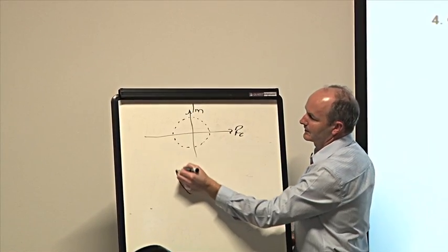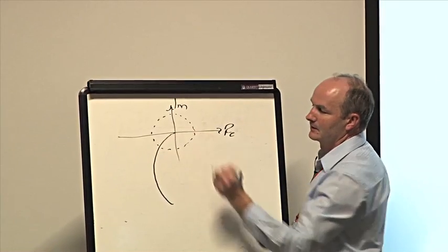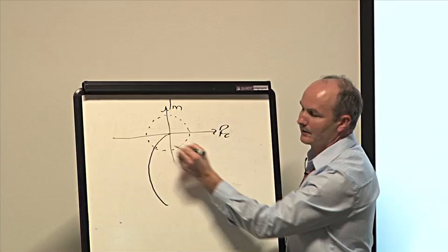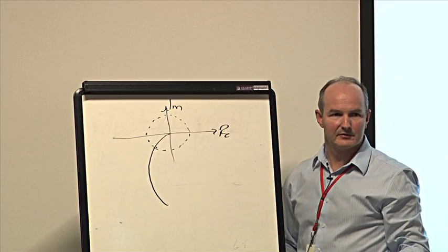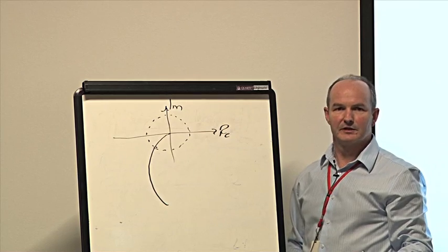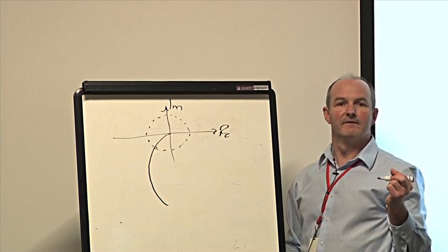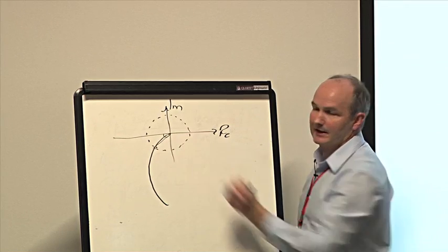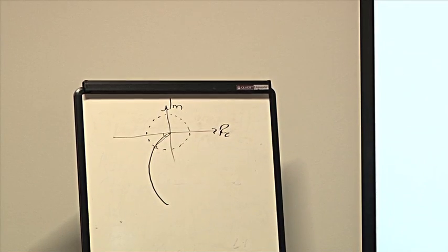If we've got a Nyquist curve coming in something like that, what's significant about that point? The gain of the open loop is 1. It's the gain crossover frequency, the frequency at which we measure phase margin. We draw a vector out to that point. That's the angle in there that corresponds to phase margin. That's the significance of the unit circle.